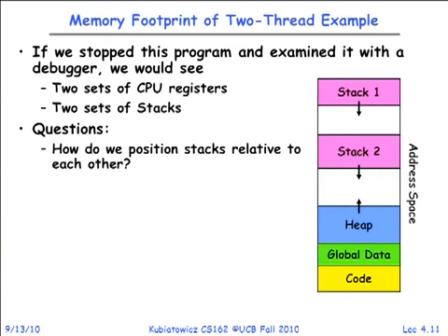Can anybody suggest how we might notice with fairly good probability that things have gone too far and our stack is overflowed? I would say you could put a warning variable at the base of the second stack, and if you ever overwrote that, immediately you know that it's about to destroy the rest. Okay, now that's a great idea. It probably wouldn't quite work the way you want, but go ahead. Another suggestion: check the offset of the stack pointer. Yeah, so you guys are honing in on an idea here that might work.